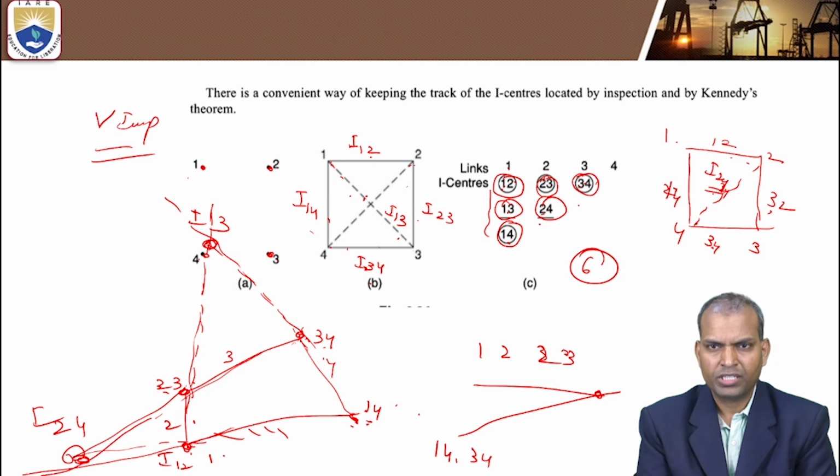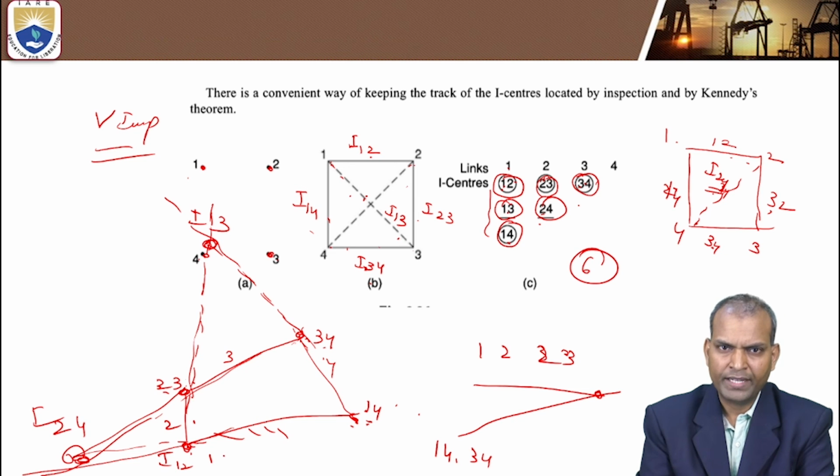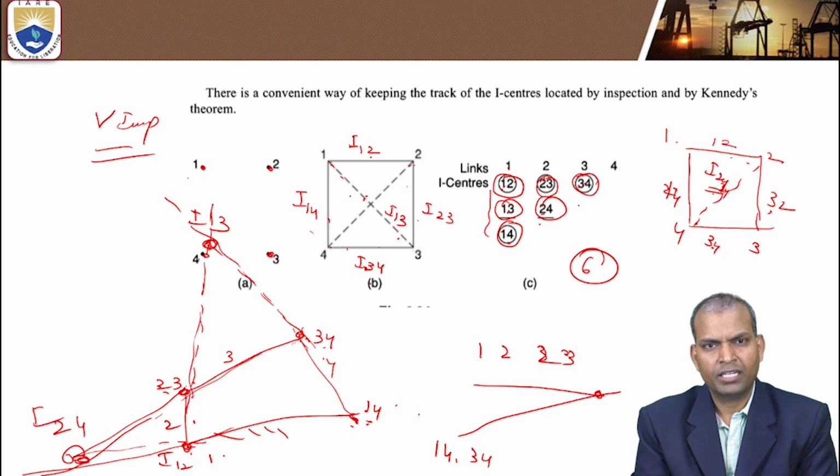But we studied with the help of a 4-bar mechanism. So in this class we have studied the description of an instantaneous center, the notation, the types of instantaneous centers, the theorem useful to locate them, that is Aronhold-Kennedy's theorem, and how to locate the types of instantaneous centers for a given mechanism. Here the mechanism considered is a 4-bar mechanism. In that we located fixed, permanent, and neither fixed nor permanent instantaneous centers.